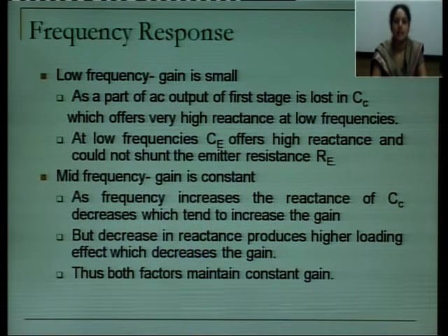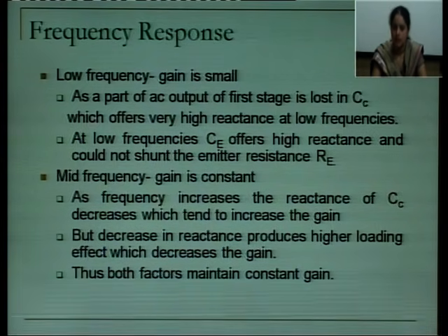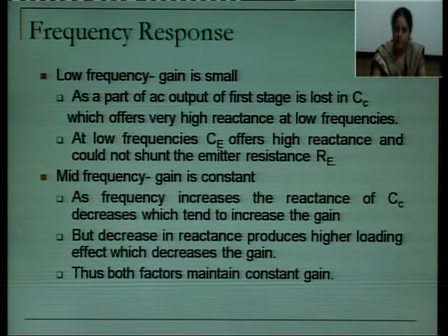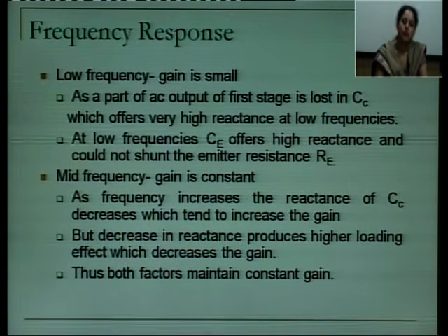As frequency increases, the reactance of CC decreases, which tends to increase the gain. At low frequency your gain was small because your reactance was very high, but now as your frequency increases, the reactance of the coupling capacitor decreases, which increases your gain. But this decrease in reactance produces a higher loading effect. The loading effect is increased, which decreases the gain. So, the gain which was increased was decreased by the loading effect of the circuit. Thus, both factors maintain a constant gain.